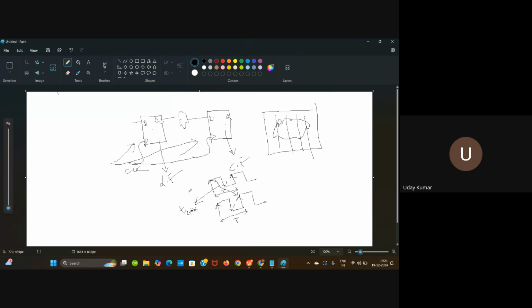And also, when the clock triggers, there will be a data here at this edge. Let us say it is some D naught. For this D naught to come to Q once the clock is triggered, it will take some time. That is called T clock to Q. So now, let us say the clock triggered. The first delay will be T clock to Q. It takes this much of time.